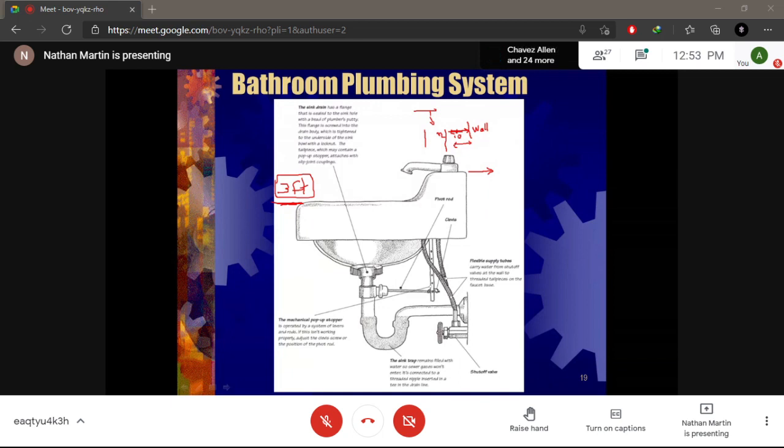Now, for your downstairs drain pipes that will carry sewage, these are typically 4-inch. Can anybody tell me the size of the pipe for your upstairs or different floors other than the ground floor, in any facility? You're talking about the toilet waste pipe? Yes, the sewage waste pipe. 3 inches. 3 inches, good.